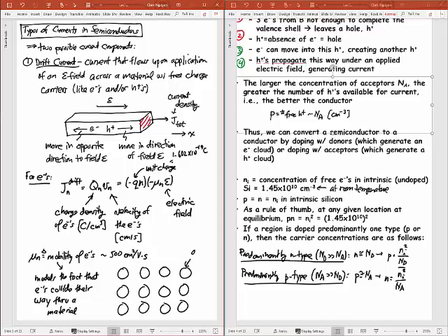Right, so each of these is an atom with some of their orbitals and that sort of thing. When an electron is moving through this semiconductor, so there's my electron, it can't ballistically just go through all of this stuff. It can if you have very few atoms between it. In some of the future types of devices people are working on right now, they will get some ballistic motion of the electron where it just goes right across because the distance it has to travel is so small, achieved by lithography.